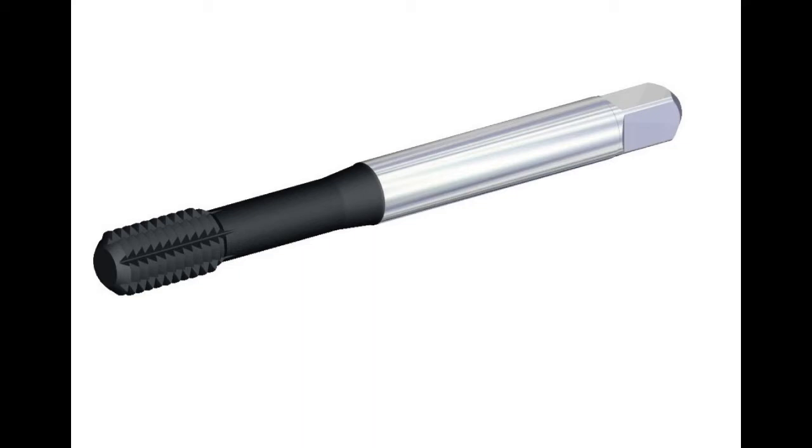There are two major types of taps as far as how they form the thread. In harder materials, you have to use what's called a cut tap, and it actually cuts material, and the hole is drilled to the minor diameter of the thread. A roll tap, like what Titan describes in his video and uses in his library, the hole is drilled larger, and the tool actually deforms the metal instead of cutting it.